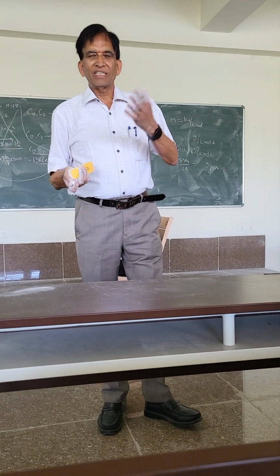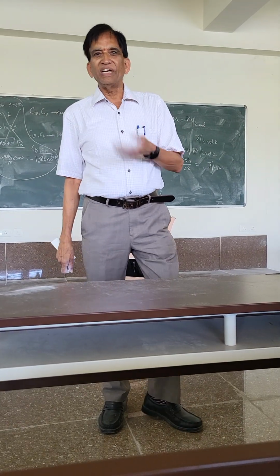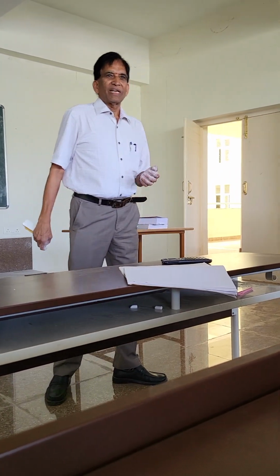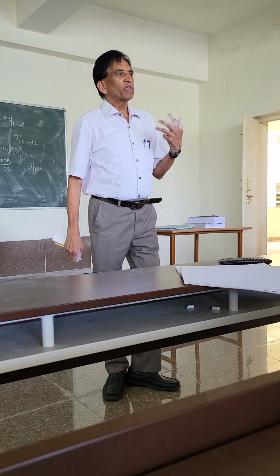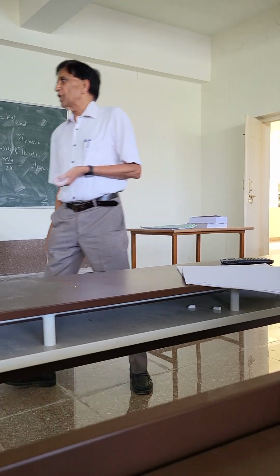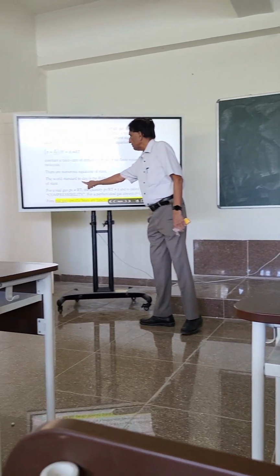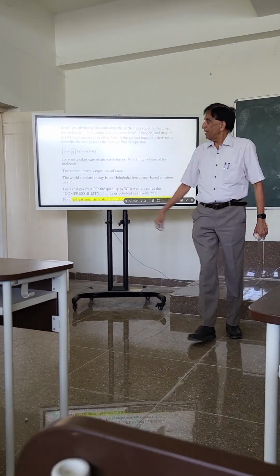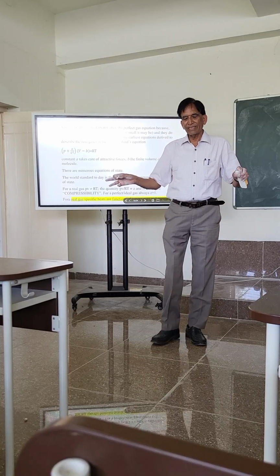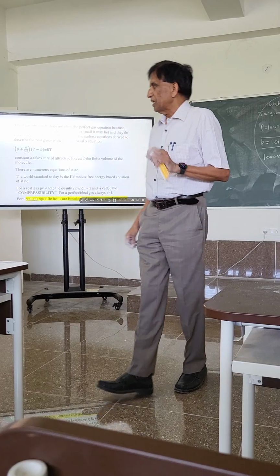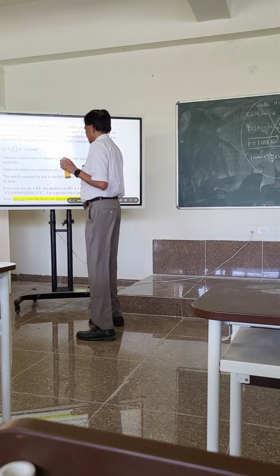And which one should I follow? As a young chemical engineer, you want to go to the field, and your boss asks you to calculate PVT properties of a gas. Which one do you use? All over the world today, the standard is what is called Helmholtz free energy based equations of state. It is neither the Van der Waals equation of state, nor the perfect gas equation of state, nor the ideal gas equation of state, nor Redlich-Kwong. They are called Helmholtz free energy equations of state.